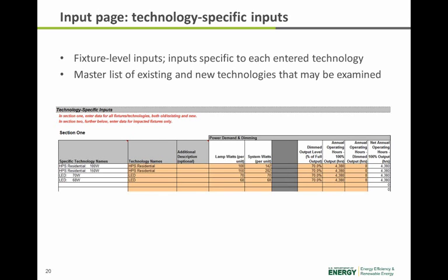Times a ballast factor, because it is possible for some technologies to underdrive or overdrive a light source, which is why the ballast factor is important. You divide those three by the input wattage, or the luminaire watt input. For LEDs, it's measured as is, meaning the entire luminaire is tested, and so the net light output divided by the power input is the result. So incumbent technologies use LER, while solid state or LED uses luminaire efficacy, but they can be compared to each other. If you're going from one technology to another, the number essentially is net light output divided by power input.